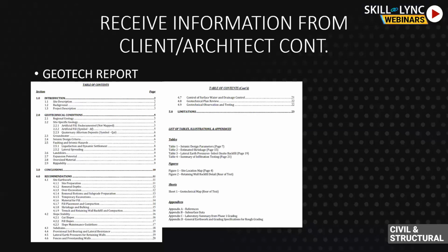Many times it happens that a geotech report will recommend three types of foundation. They'll say okay, you can go with shallow foundations, wherein you have isolated footings, or you can go with a raft footing or a mat footing which is shallow enough, and that would serve the purpose. Along with that, they'll also say you can have end bearing piles which you'll have to bear at a depth of 20 meters, or 30 meters.